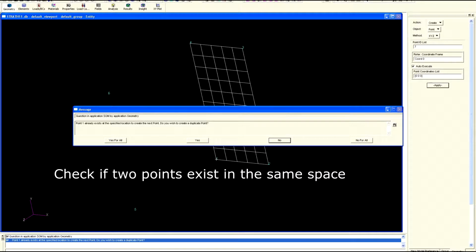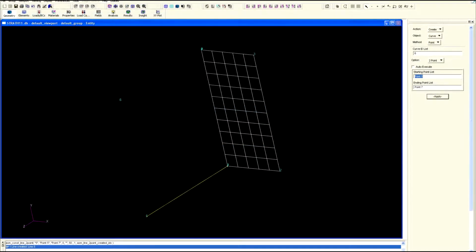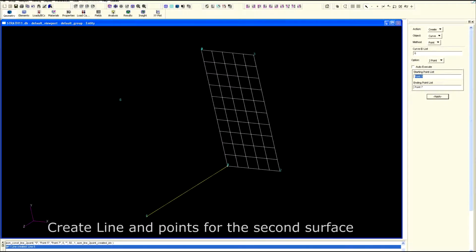Now you need to check if these 2 points do share the same place in 3D space. You can do this on the right hand side drop-down menu and look for, I believe under elements, the word view. Put a box around the origin of the 2 panels and you will see a readout confirming they are 2 points, both with the same coordinates.